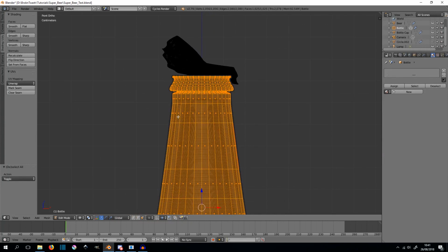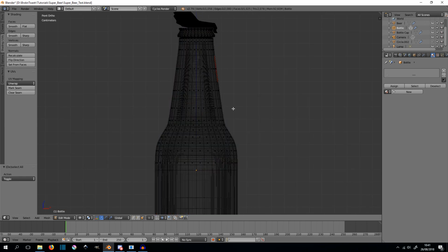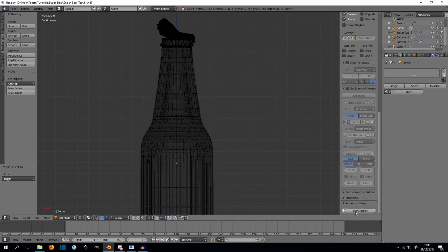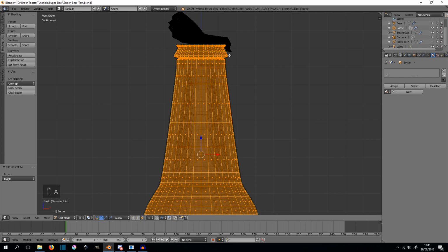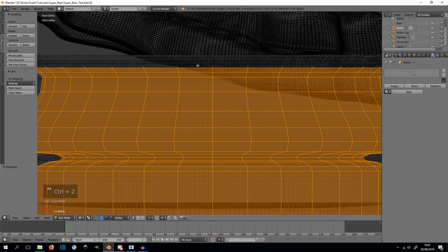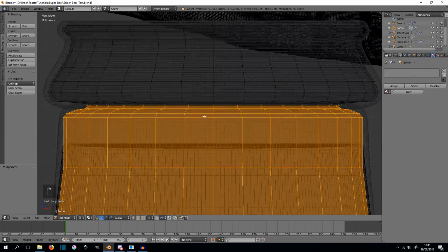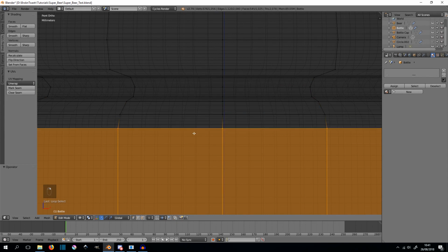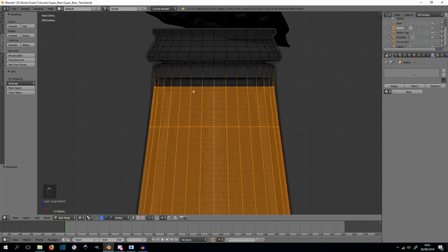So the way I will do this is I go to edit mode in the bottle. I select everything using A. I always forget the screencast keys, unbelievable. So I go into edit mode, select everything. I'm going to deselect these top vertices, because I want to make an object that will represent our beer. So I go all the way up like so, perhaps not as high.